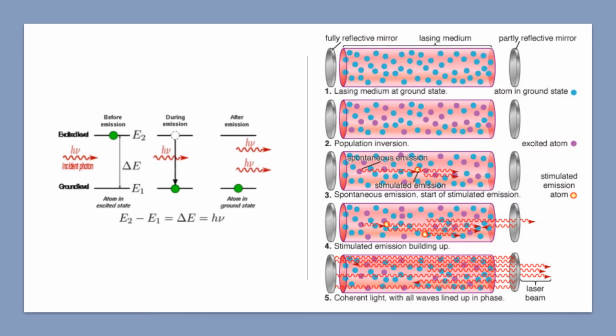Finally, direct conversion of electrons is where we use electric energy and convert it directly to light using a semiconductor laser. Then the electrons are triggered or stimulated by an incoming photon with the specific energy to emit photons that are in phase and have the same direction and the same wavelength as the incident photon, resulting in a beam of laser light. The rate of stimulated emission of radiation is proportional to the population at the higher energy level and to the density of the incident photons.